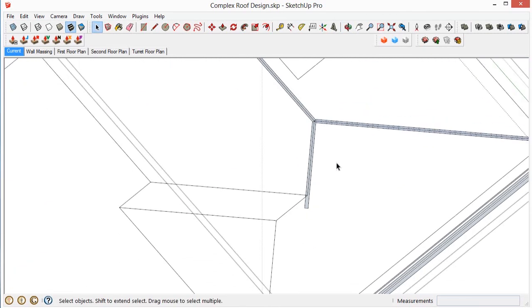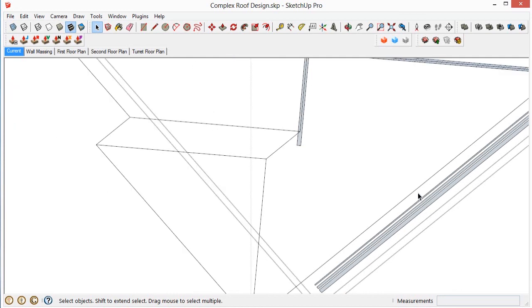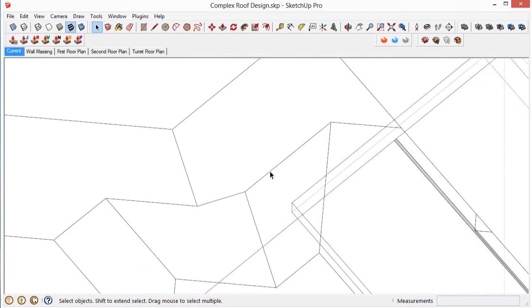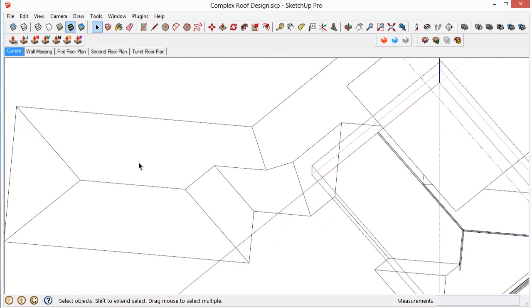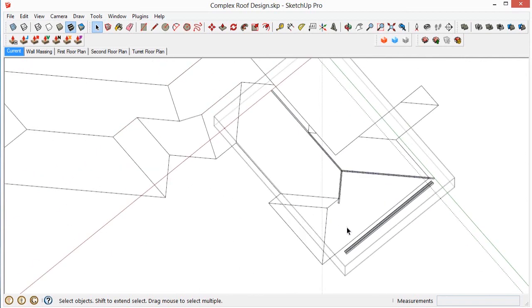So we'll continue doing this, basically distributing these rectangles that represent the structural members 2x, 4x, 6x, where I'm just going to do it arbitrarily here, where I think maybe that thickness of structural member is necessary. So for example, I'll probably make these 4x's, these two hips 4x's, this ridge 4x, this valley 4x. I'll make the rafters 2x's. I'll make this ridge here, this valley, this blind hip here, I'll make those 4x's. And these over here 6x's, and so on. So I'm just going to go through it as quickly as I can.